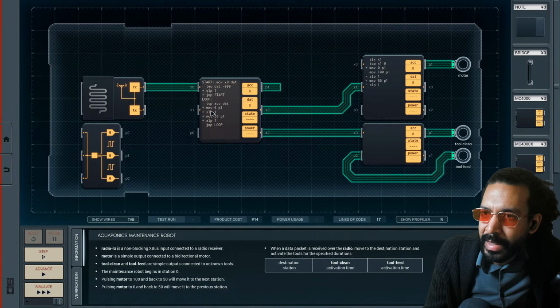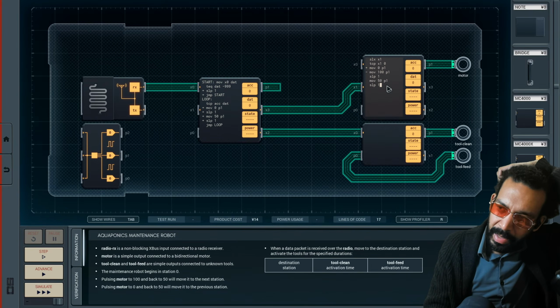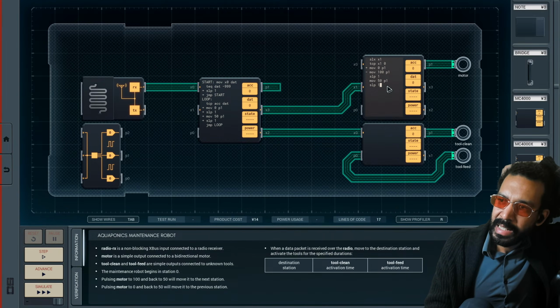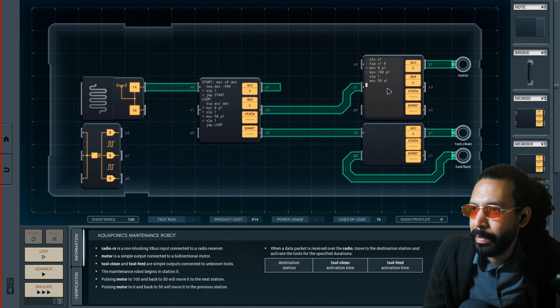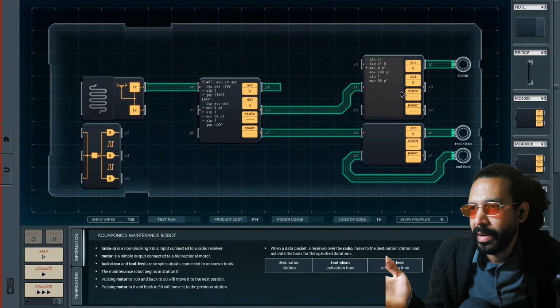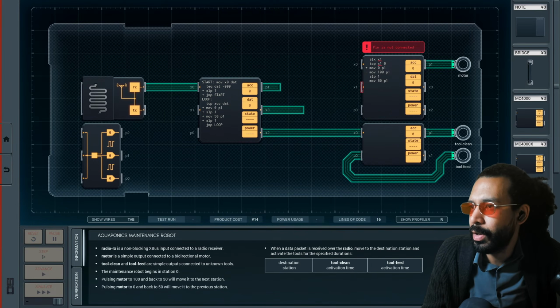Oh, you know what? This is less lines of code than I thought it was. We're still separating it. We can put it back together later. Okay, so after that, regardless, we sleep 1, move 50 to P1, and then sleep 1 again. And this last sleep 1, we don't even need to do, do we? We can just sleep X. So back to the start. There it is. That fits on the small chip.